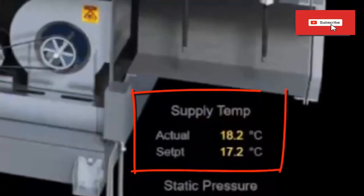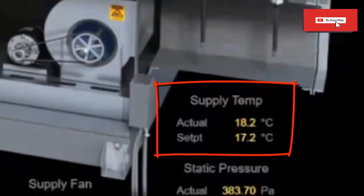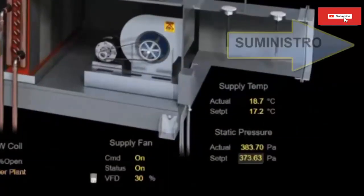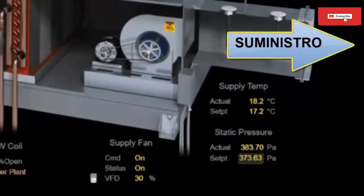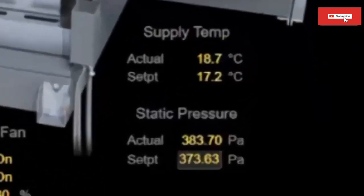8. Supply temperature. In this case, the set point has been placed at 17.2 C. At this moment, the temperature that this air handling unit is achieving is 18.2 C. 9. Static pressure. It is the minimum pressure that the distribution must have to get the air to all the outlets. In this case, the set point of this installation is 373.63 pascals. However, the current pressure of the facility is 383.70 pascals.